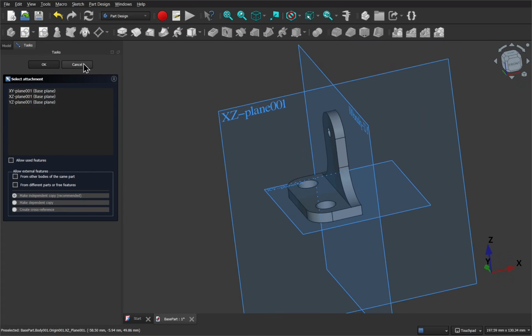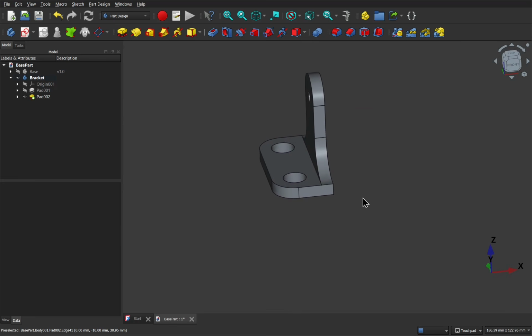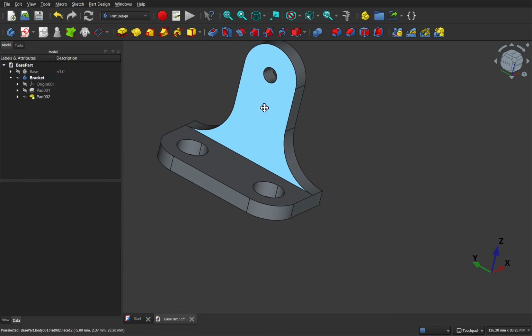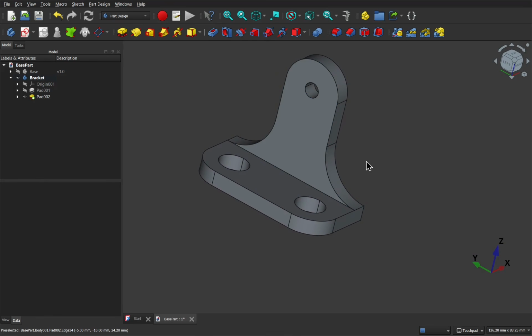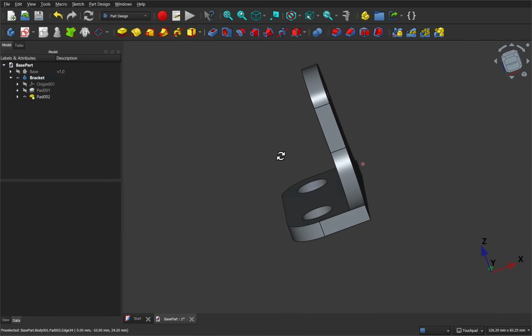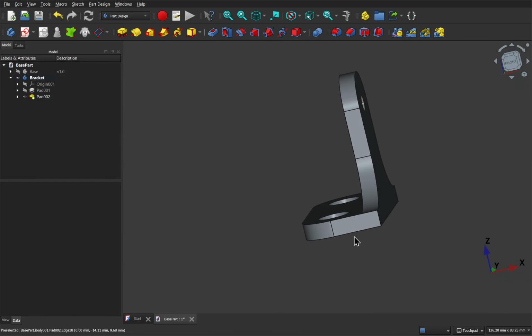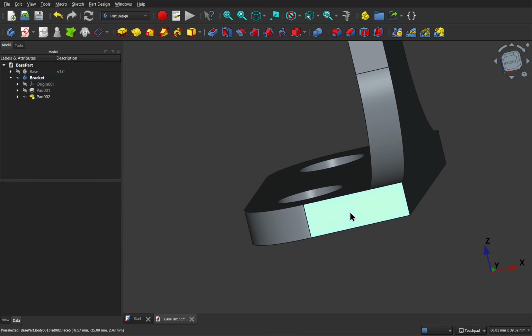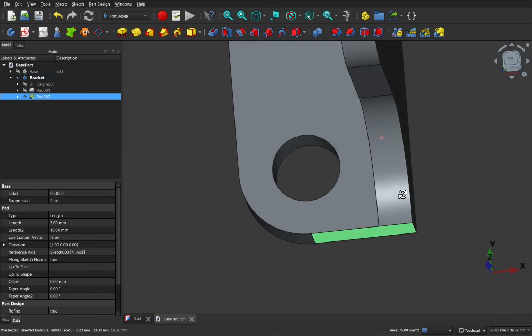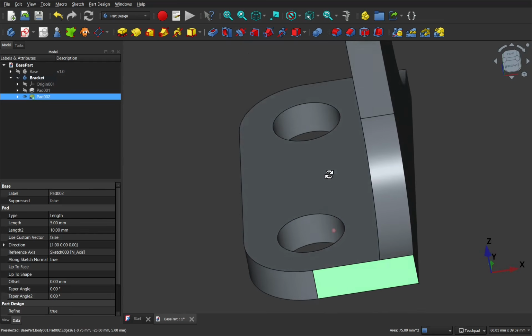There is another way. Let's cancel that. We've been using attachment modes where we've attached to the faces. So I'm looking for a planar face that I can attach to from the XZ plane. The only one I've got is this one here, planar as being the vertices are all along the same plane.